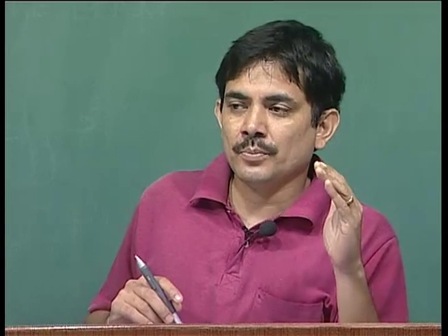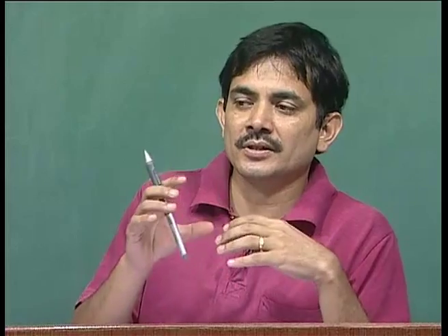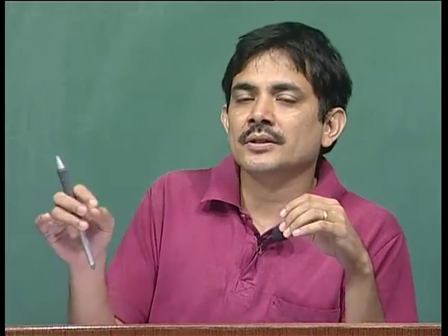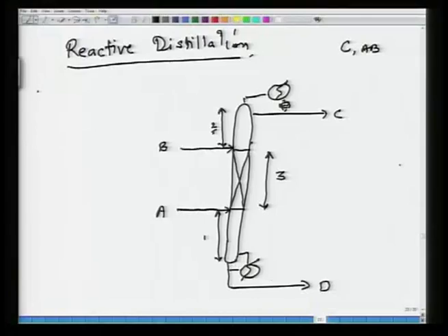There is an azeotropic composition, you add an entrainer, because of that entrainer phase separation occurs, organic rich, water rich, and because of that phase separation the azeotropic composition gets crossed, okay, and then you can get pure A and pure B, which otherwise if you had taken it as one you would not have been able to separate. Here, because of reaction, some azeotropes can get reacted away. Okay. So, let us just, before I get into control, advantages.